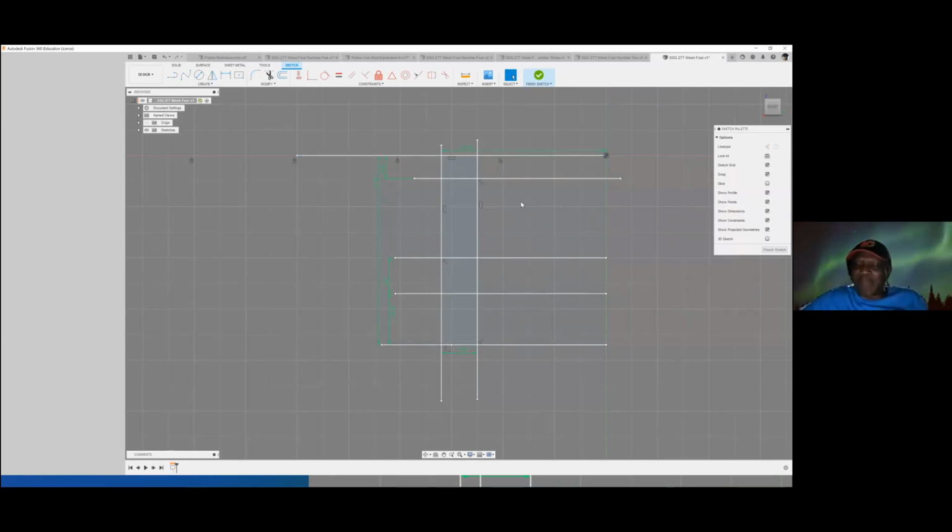And I can pick the lines one by one. I can also pick two lines. I can choose two lines and press X, and both of them are now construction lines. Okay, this is a construction line, this is a construction line, and you know by the lines being dotted instead of straight. So it is the dots, not necessarily the color, but the fact that if it's a construction line, you will see dash, dash, dash.